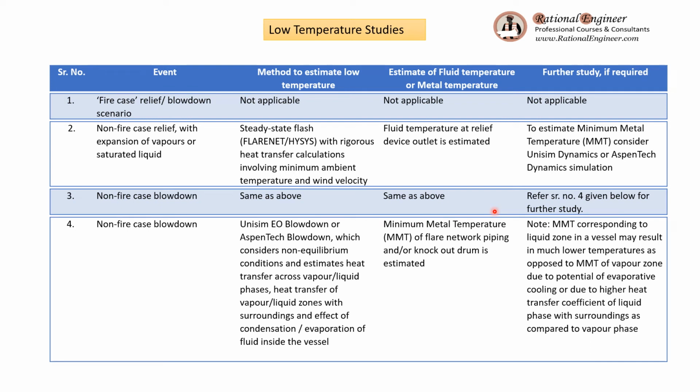Sometimes the liquid zone in the vessel may result in low temperatures as compared to the vapor zone due to an effect called evaporative cooling. The intent of this exercise is that the minimum metal temperature estimated during such low temperature events should not be below the lower design temperature of the piping.